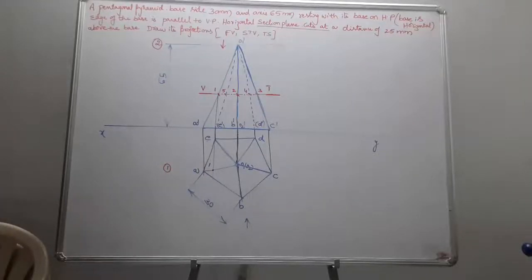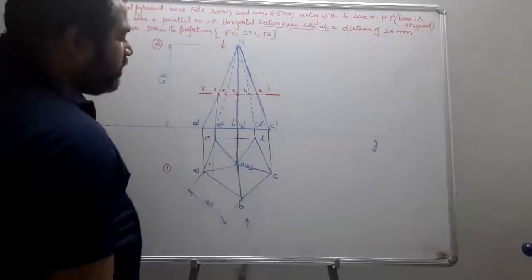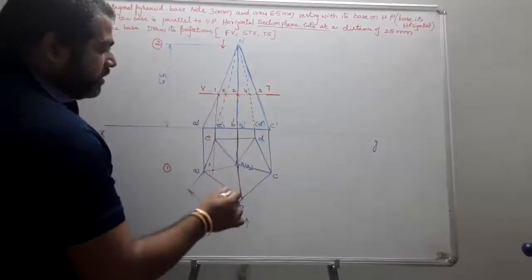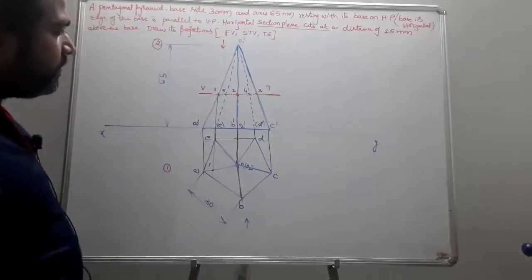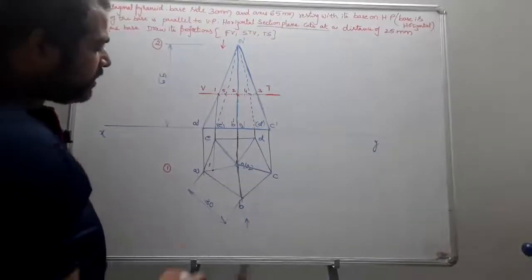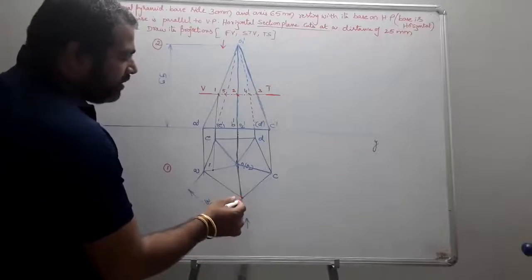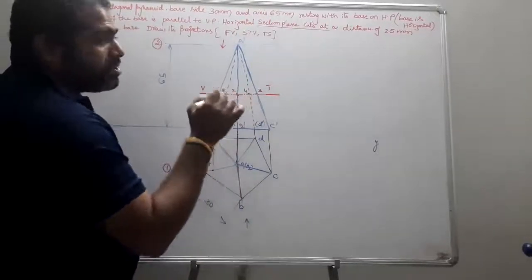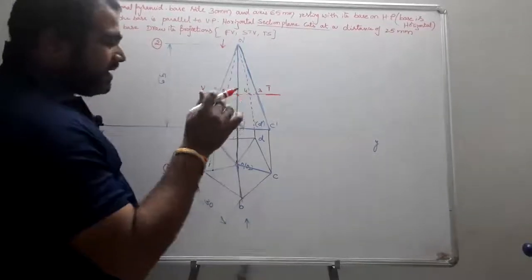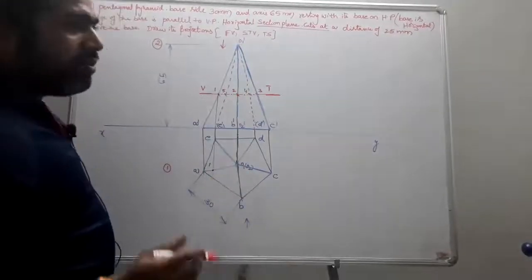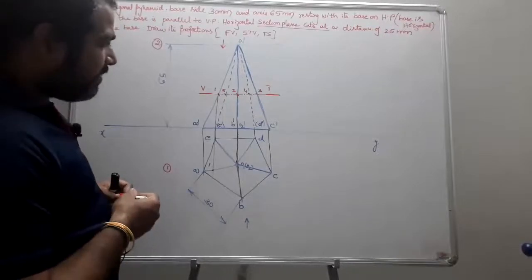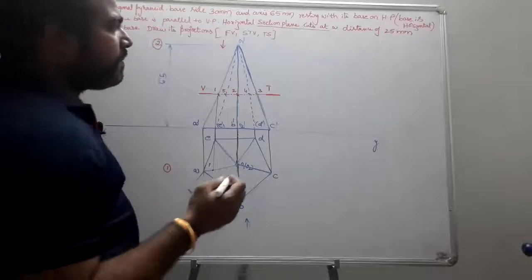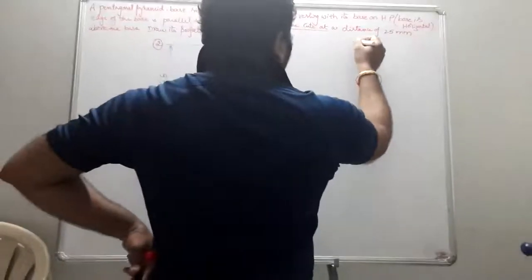Now if you see, there is an obstacle here. If I just consider my point 2, it is going to be obtained here. But in this consideration, my point 2 should not be here. It should not coincide with the OB edge. It should cut the solid OB slant edge, but it is coinciding. When a problem arises in this type of situation, you just create a true slant edge. We just have to create the true slant edge.